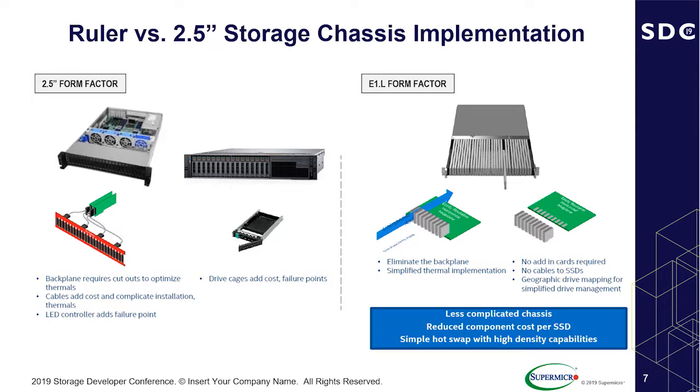Any other question? Yes? It's not on your slides, but you mentioned that E1.S has multiple different versions. So you're focusing on one version of it. Maybe a little bit about what the other versions are? The one that I've seen most prominent at Flash Memory Summit, last month or August, is a 25 millimeter wide one where they basically take the 9.5 millimeter version, pretend like this is short, and stick a freaking huge heatsink on the edge, just on one end, so it's not even symmetric, which could actually be kind of okay.